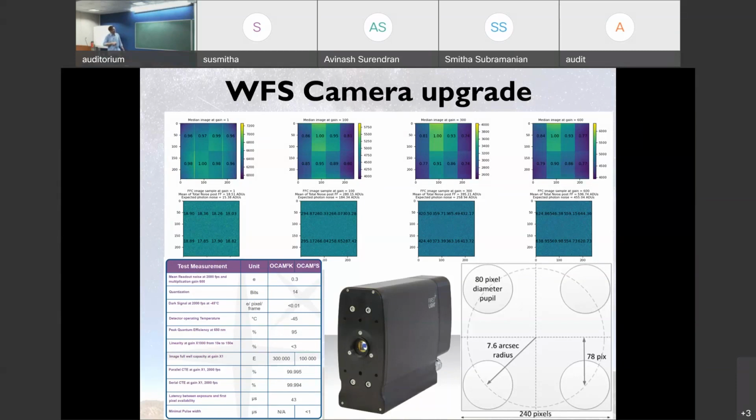But when you put a high voltage amplification, the noise, meaning the photon noise, increases by a multiplication factor of √2 in addition to the usual square root of the signal factor that we are used to. In addition, you get this checkerboard pattern with a huge variation between the quadrants. And this one is the uniform image after flat fielding, showing the noise remaining in the camera, measured as a standard deviation, the total noise in each of the channels.